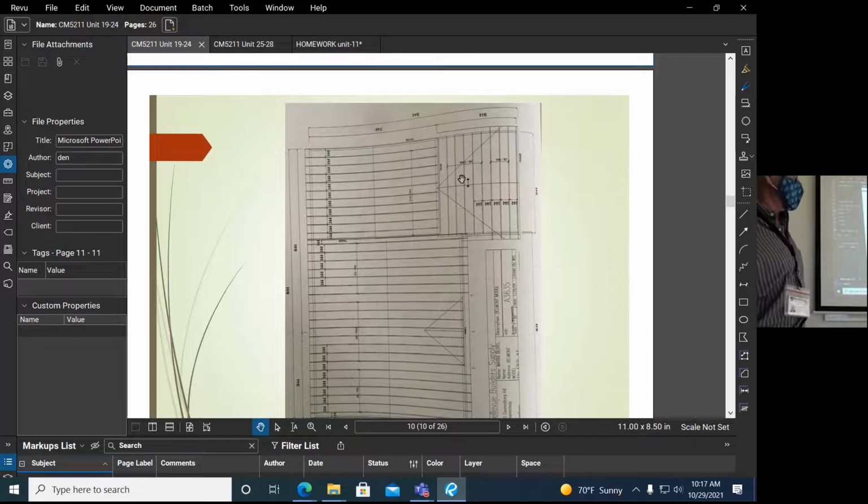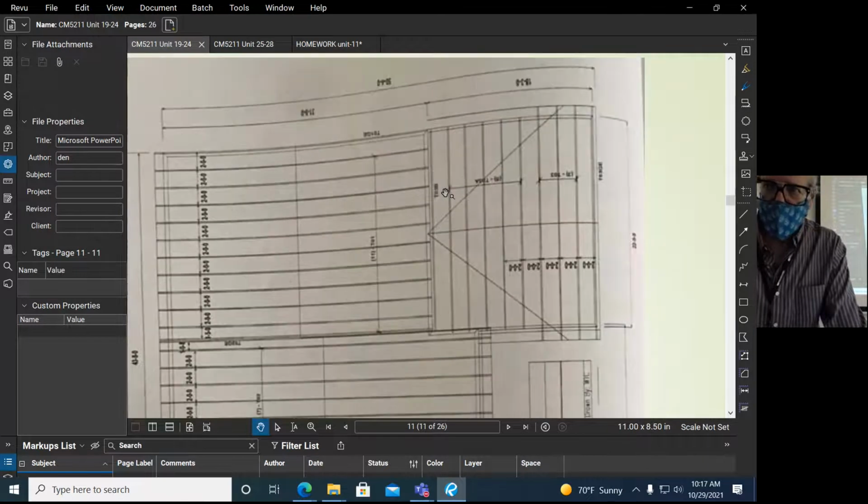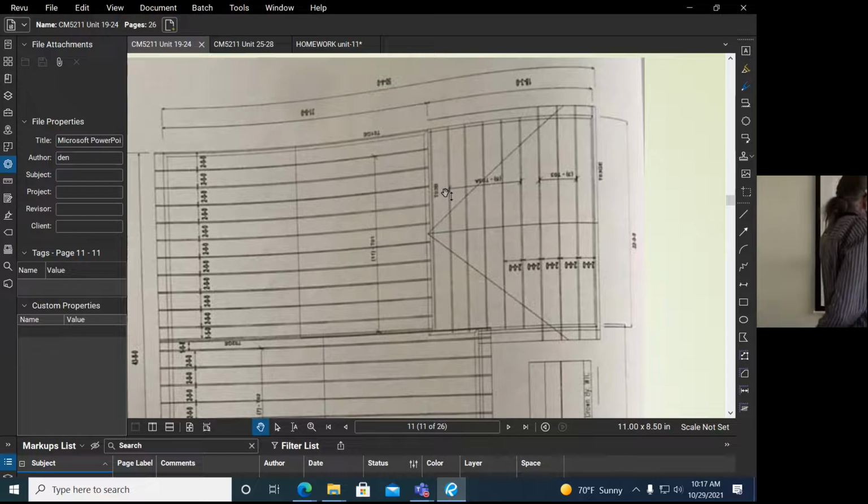A typical framing plan layout. This is also from the book. A framing plan will tell you which truss member is there, that T01GE, that's the gable end truss. And then the spacing here, and then what the trusses are. These are the inner trusses.